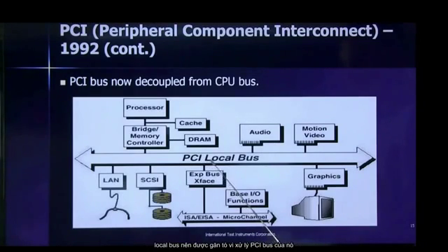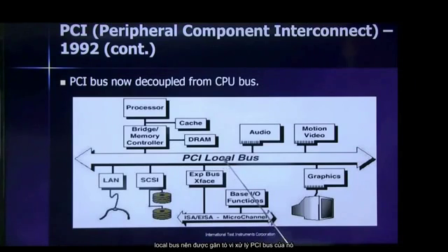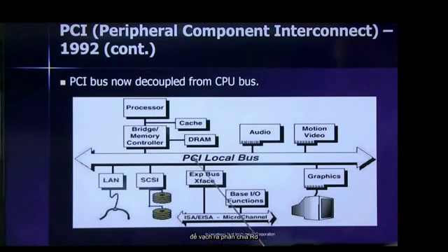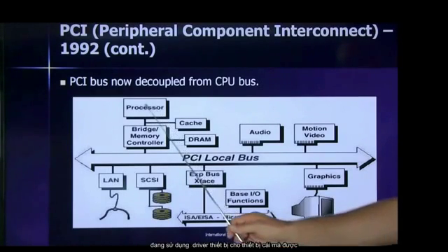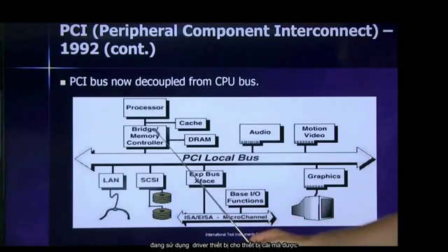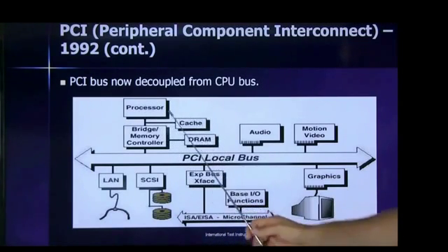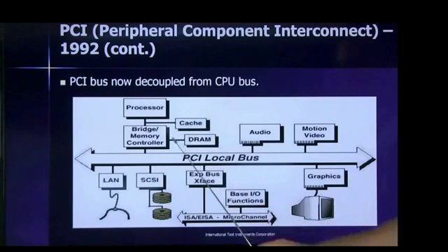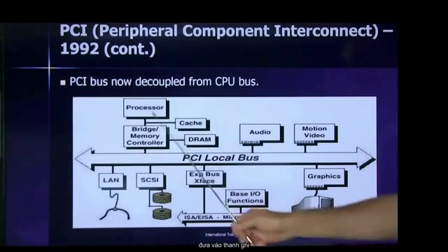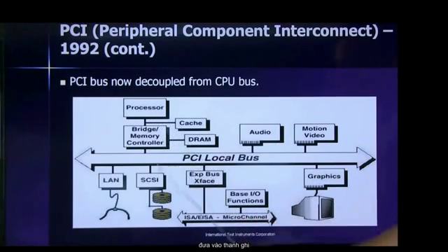It's actually a little bit of a misnomer here in this picture to call it a local bus because it's not actually local. Local buses should be attached to a processor, but it's a PCI bus. The way the bridge works is that the operating system configures the bridge to map a portion of the processor's address space to PCI address space. These two address spaces are completely separate.